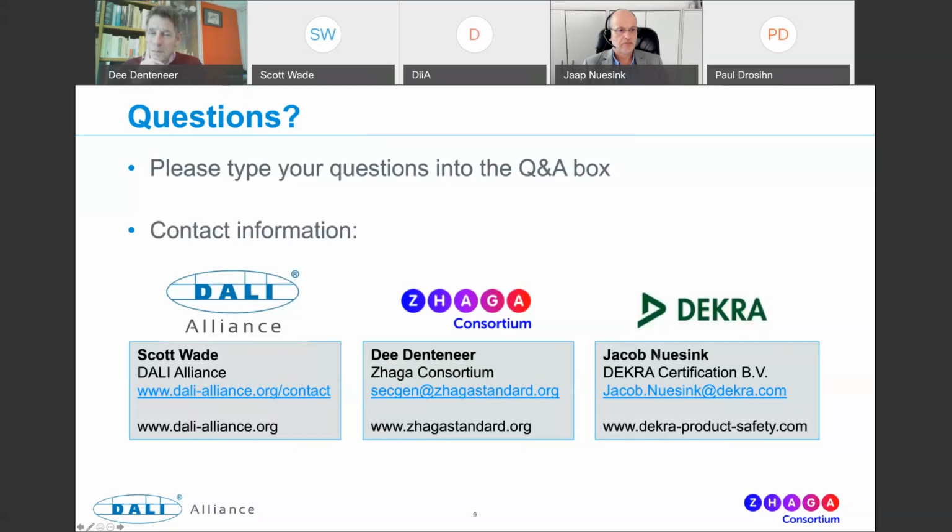Okay. As to the question which seems to be addressed today, did you speak about an adjustment to the Zhaga Book 18 connector for nodes on top? It's not an adjustment to the connector. It's including a different connector, the ANSI C136.41, into the architecture. So the Zhaga connector, as we've had in our specification in the architecture, is as it was originally published, I think, in 2018. But we add an additional option, which is this ANSI C136.41 interface, a different connector.